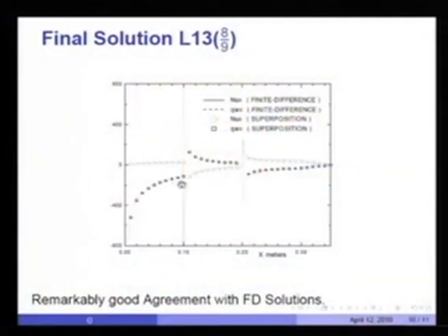The moment, however, the wall temperature moves from 50 to 80, remember 80 is less than 90, then the layers of fluid close to the wall are still at a temperature close to 50, and although the wall temperature is 80 now, heat actually flows from the wall to the fluid, although the free stream temperature is higher than the wall temperature.